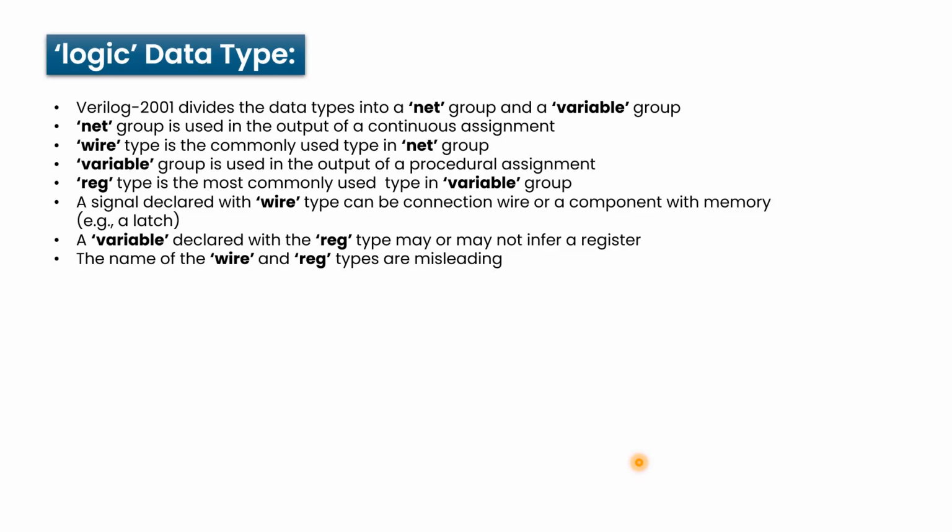And here I would like to mention an important point: when we declare a reg data type, many of us get confused that this is a flip-flop or a memory element or a register. But that is not the case. The reg data type doesn't mean it is a flip-flop or a register. The implementation or realization of hardware completely depends on our Verilog coding style.